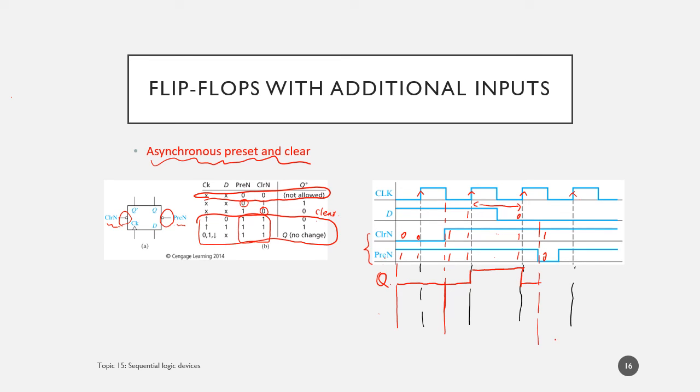So 1 and 0, now this is what? So preset is 0. Here we can call it preset or preset state. This preset state means Q will equal 1, even though we don't have a rising edge. As I said, this is asynchronous, so it overrides the clock. So it still sets the output, and here it changed to 1, 1, so not active.